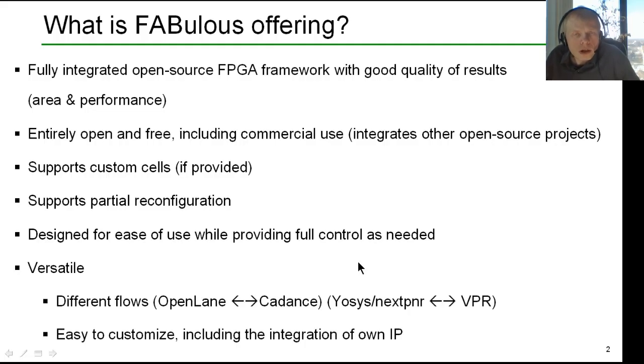What is the Fabulous framework offering? It's a fully integrated open source embedded FPGA framework which uses a lot of tools and algorithms under the hood to provide good area and performance measures. It's entirely open and free, including commercial use, and it integrates a lot of other open source projects. It supports custom cells if provided, for example, for configuration storage or switch matrix multiplexers. However, if you don't provide those, we can fall back to standard cells if needed.